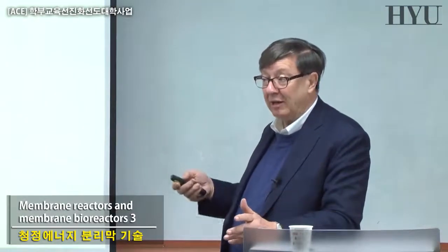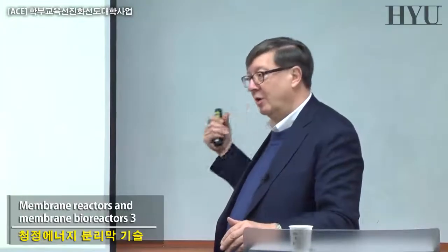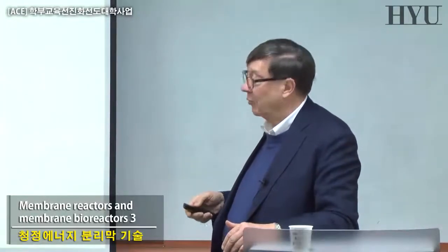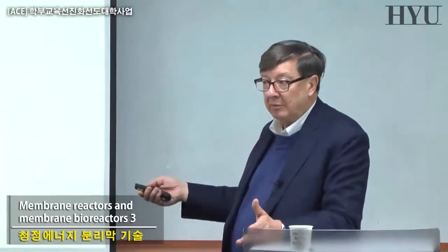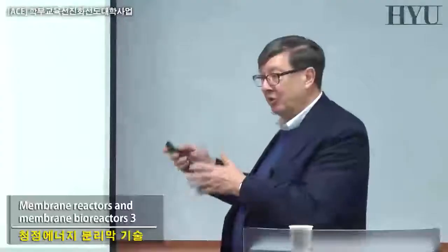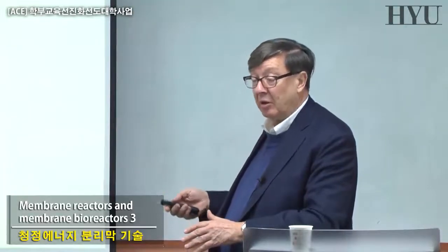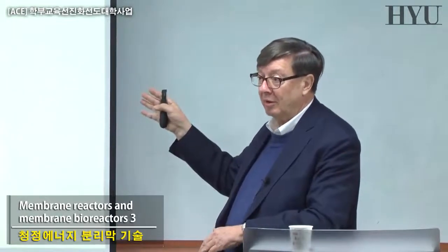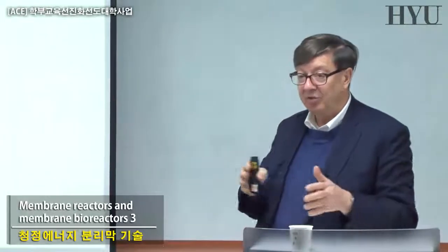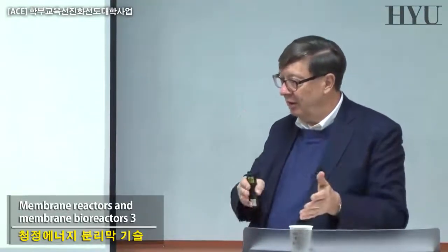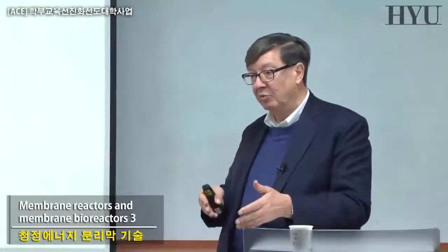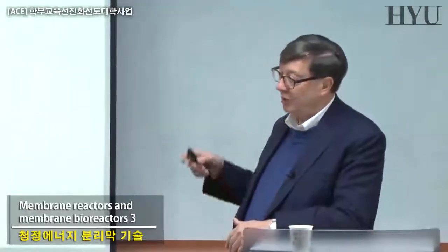I don't know if you are aware that today in desalination, if you were in Jeju last week, when I was, instead of being here in your class, people are already assuming it normal to have integrated membrane operation in desalination, which means you don't have only reverse osmosis. You have all pretreatment to reverse osmosis based on microfiltration, ultrafiltration, nanofiltration, and similar. And now you have also the post-treatment to reverse osmosis to increase the recovery factor, to keep control of the brine disposal, such as membrane distillation, membrane crystallizer, etc.